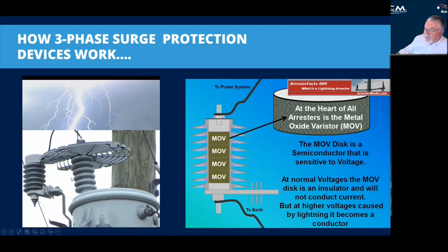There are surge protection devices on big commercial city power poles and things like that. That's what these devices are on these transformers. These are surge protection devices, and they'll absorb lightning strikes and other things. So basically they're MOVs, or metal oxide varistors, a variable resistor. And these are very large, and you see there's a series of MOV discs inside. In this one, they have 4 large MOVs.